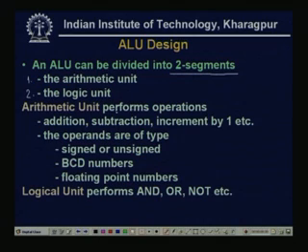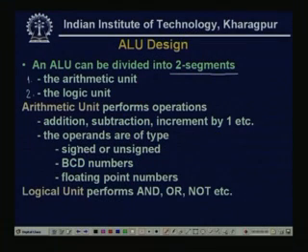The arithmetic unit performs arithmetic operations: addition, subtraction, multiplication, increment by 1, decrement by 1, etc. Obviously it operates on some operands, and these operands can be signed or unsigned, binary coded decimal numbers or BCD numbers, which we read earlier, or floating point numbers.